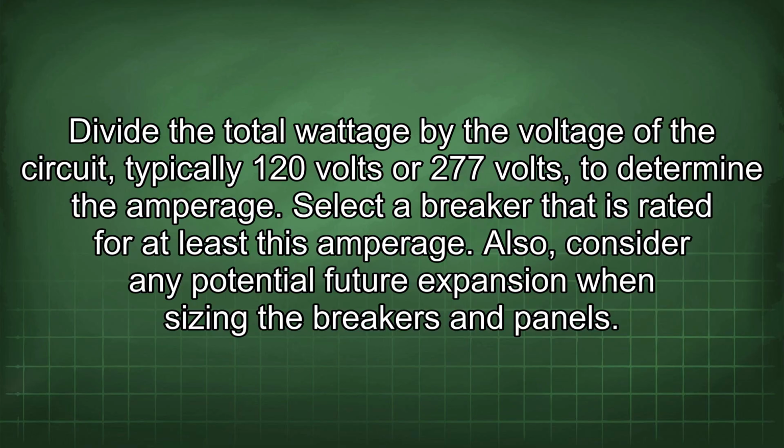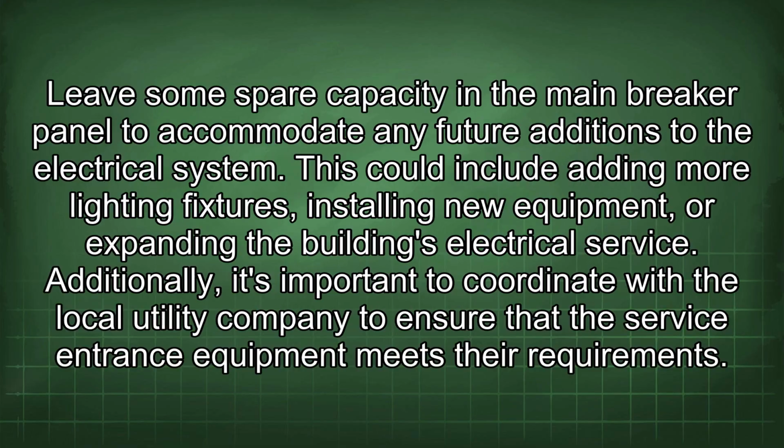Also, consider any potential future expansion when sizing the breakers and panels. Leave some spare capacity in the main breaker panel to accommodate any future additions to the electrical system. This could include adding more lighting fixtures, installing new equipment, or expanding the building's electrical service.